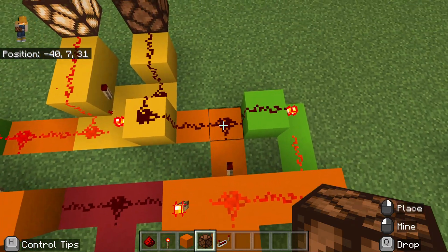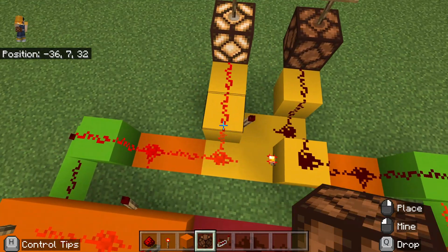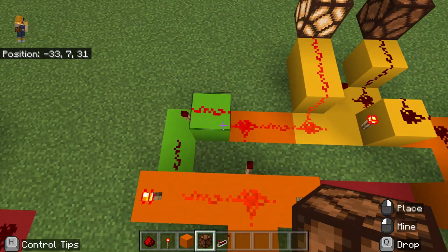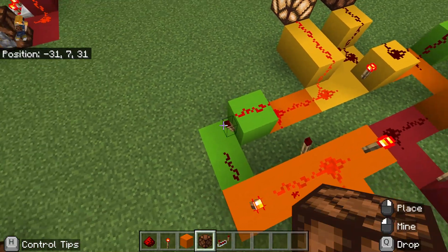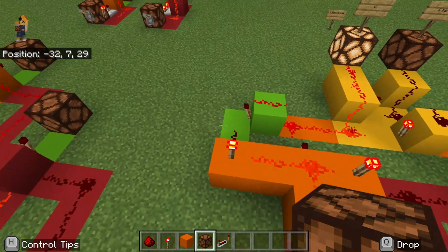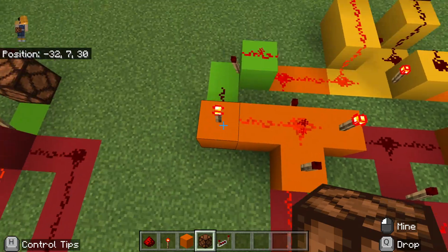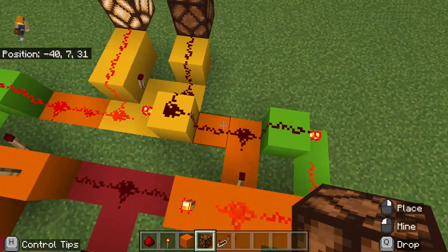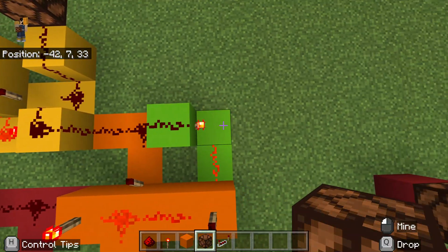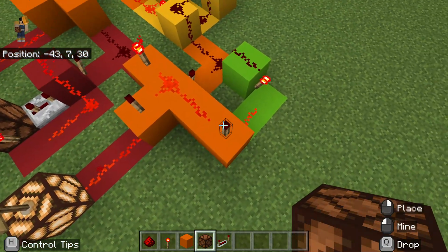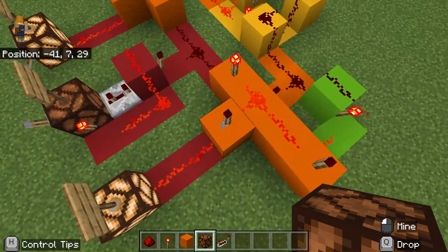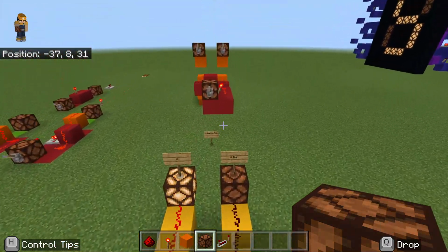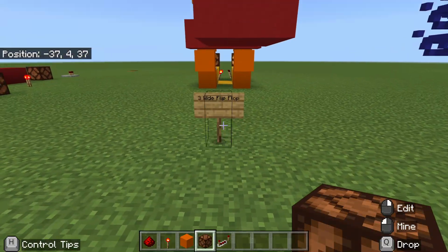That means all of this redstone here is off, turning on this redstone torch, latching it, and that means that this redstone here will turn off, allowing this redstone torch to turn on, and that will turn off this torch, allowing this side here to toggle. Meanwhile, this side here will turn on, and this torch will turn off, so this torch disables this AND gate. And that's how it works.